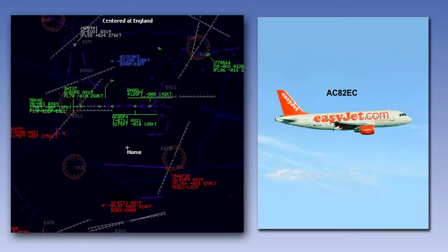Direct recognition of the aircraft identification of a Mode S equipped aircraft radar label. Mode S secondary surveillance radar is unique in that it identifies the unique 6-digit hex code assigned by ICAO to the aircraft upon manufacture. This identification code is not displayed to the controller, but is converted to another recognizable label. This label is either the assigned label for that flight, the flight number or call sign, as shown here.